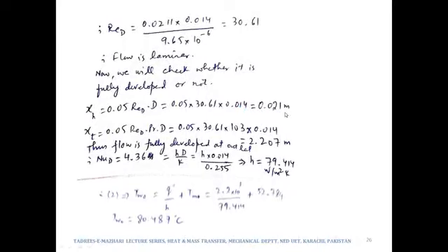It means that for some initial portion of the pipe, the flow would be under the entrance region, and after this 0.021 meter length, it will become hydrodynamically developed. Similarly, the thermal entry length, fully developed length, would be 2.2 meters. Again, this is less than 3 meters. So for 2.2 meters, that length would be considered as entrance length for temperatures, whereas after 2.2, it would be considered as fully developed. It means that the flow is fully developed at outlet, both hydrodynamically and thermally.